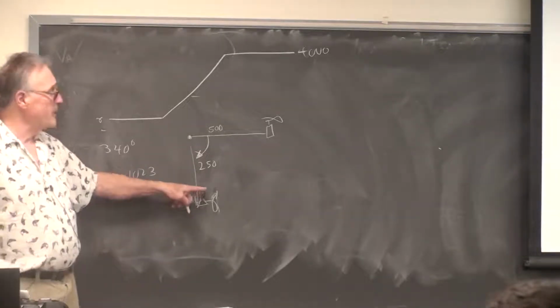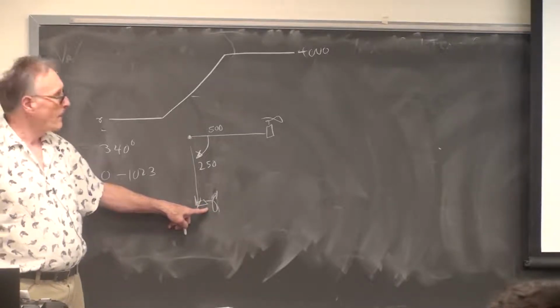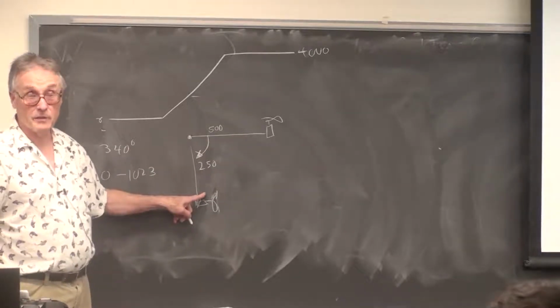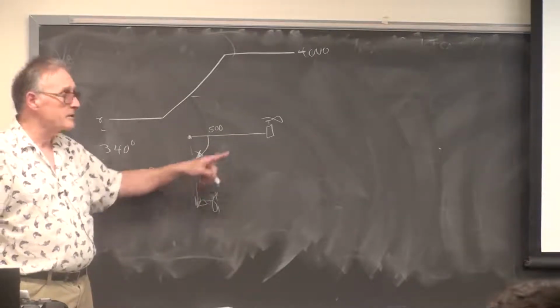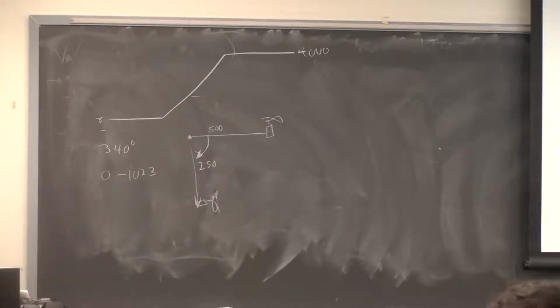Let's say now we turn the system on and the pendulum is hanging straight down. We'd like it to be horizontal. That's a big error. In fact, it's one of the biggest errors you can get in the system. It's 90 degrees. That would suggest that we want to turn the motor on full power so that it quickly goes to the 0 position.